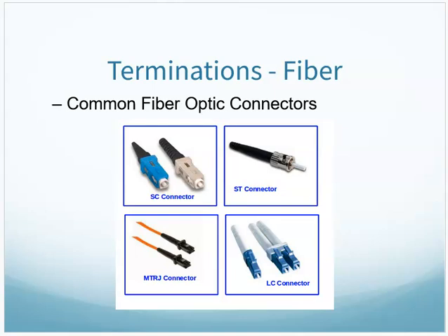They mentioned some fiber terminations. The common fiber terminations we run into, well, some of the very first fiber terminations was an ST connector, this kind here. That was, I would say, mostly replaced by the SC connector. That was like the next evolution. This just kind of plugged in. Then some places adopted the MTRJ, which allowed both fibers into one connector.